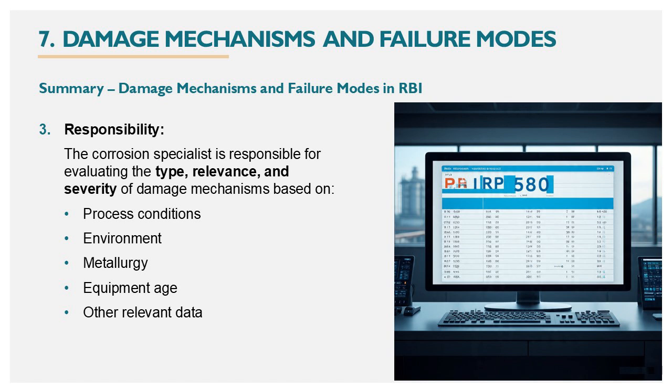Number 3 of the summary of damage mechanisms and failure modes in RBI is responsibility. The corrosion specialist is responsible for evaluating the type, relevance, and severity of damage mechanisms based on process conditions, environment, metallurgy, equipment age, and other relevant data.